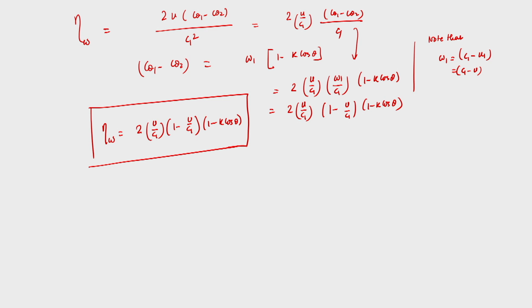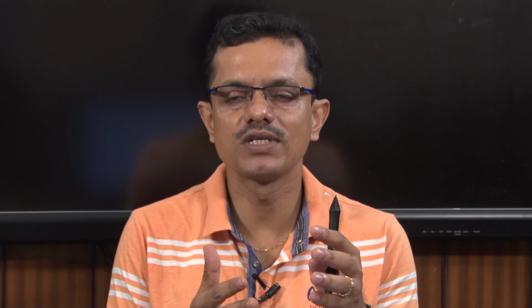Now our target will be to obtain maximum wheel efficiency. As I discussed, the deflection of the jet can be achieved by suitably designing the bucket. If it comes out exactly in the opposite direction of the incoming jet, we might get higher wheel speed, but that creates another problem: it may strike the preceding jet, which is continuously coming as the wheel rotates, and instead of higher wheel speed it may create resistance to the wheel rotation.